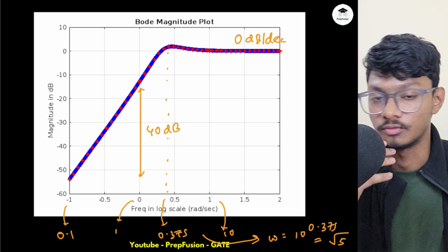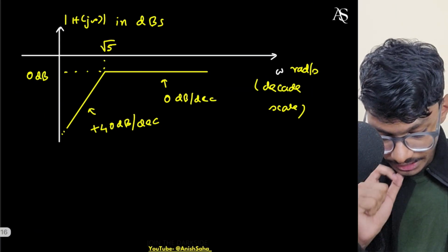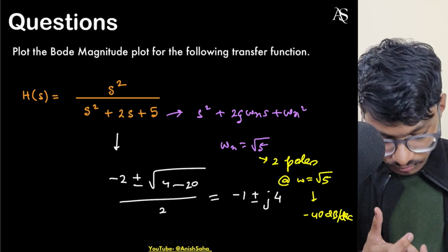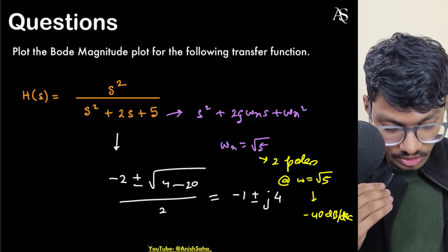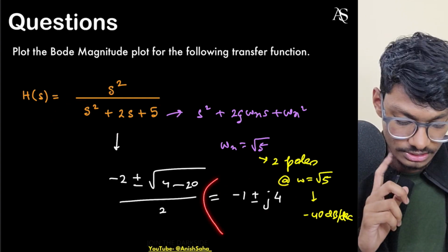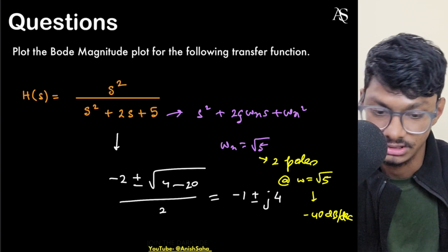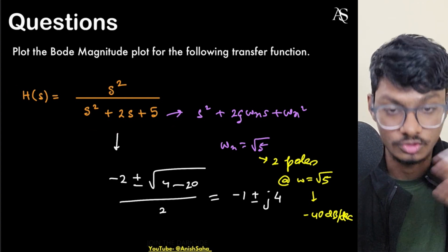But the thing for which all of you came, the 3D Bode magnitude plot. So here, can you see, where does my magnitude go to infinity? The magnitude will go to infinity at poles. So what are the poles at these frequencies? These are the frequencies at poles. So here, what does this represent? These poles represent where my magnitude, or this transfer function, goes to infinity.